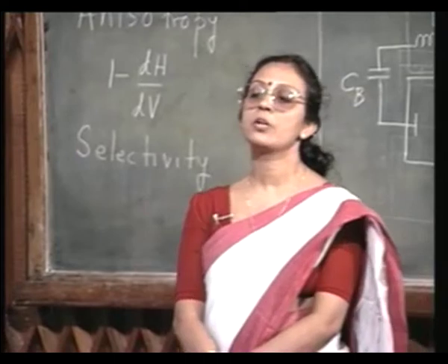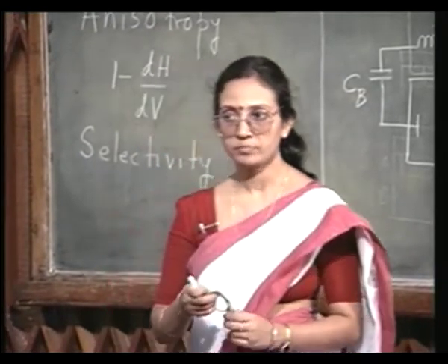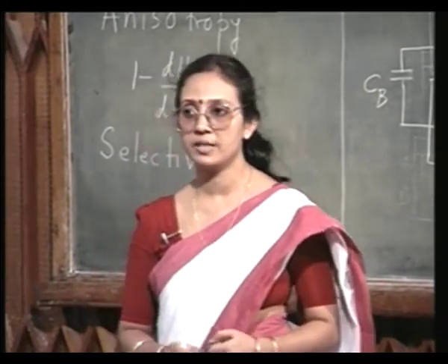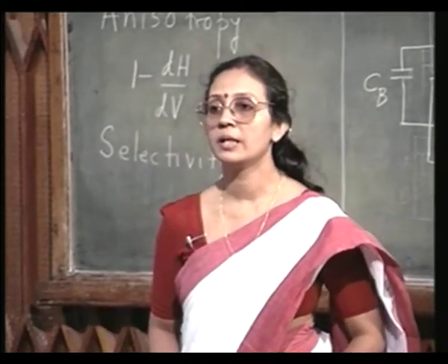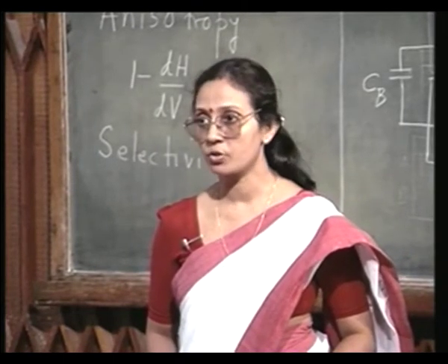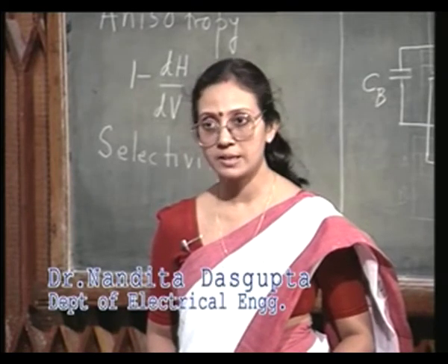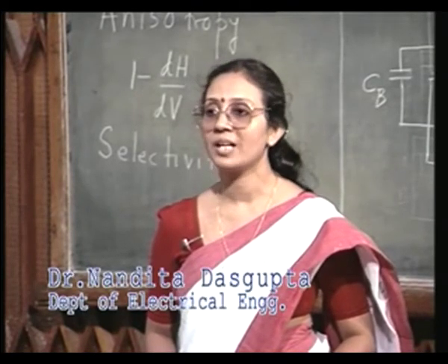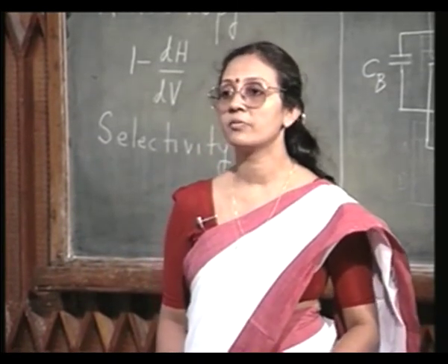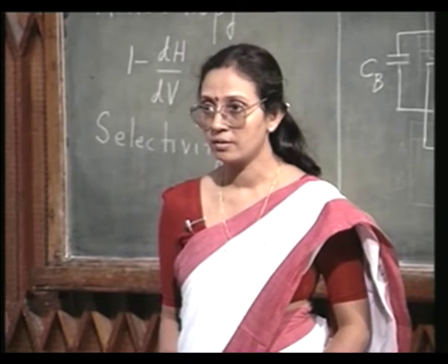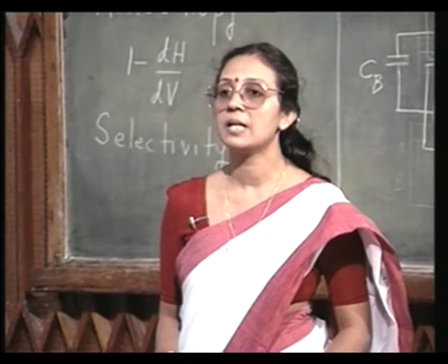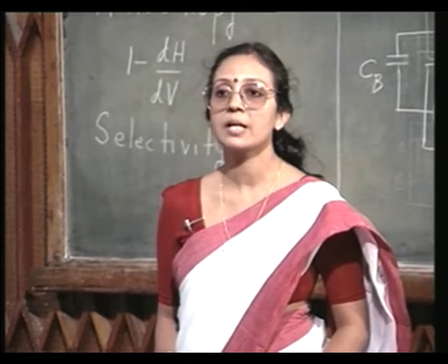Now, why am I harping on this ion bombardment energy? Because I have introduced the topic of dry etching by telling you that there are certain limitations of anisotropy in case of wet chemical etching. So, obviously, one prime reason for moving towards dry etching is to realize perfectly anisotropic etching, and ion bombardment is going to help us in realizing a highly anisotropic etching system.